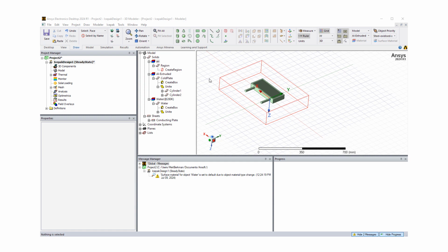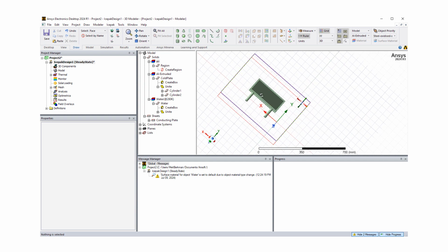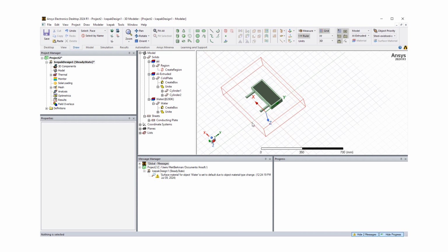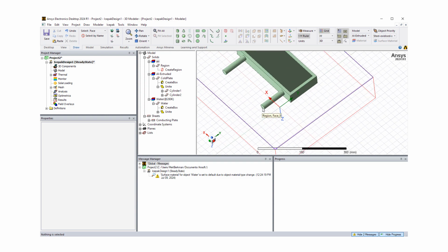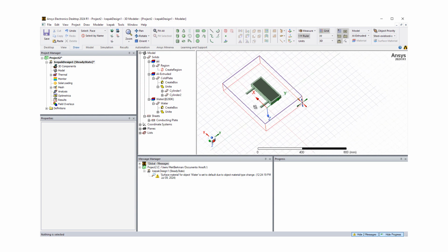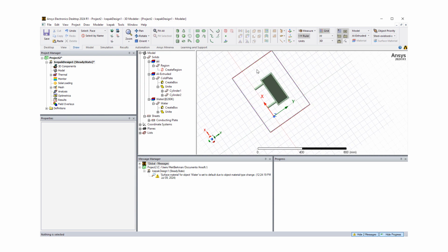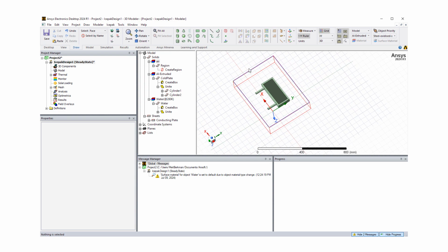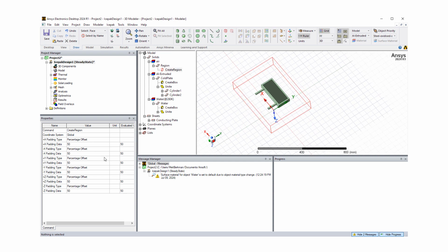In the next step, I'm going to readjust our enclosure size so that it's doing the right things. What I'd like to do is take the face, the Y minimum face, and align it with the inlet of these pipes, and also maybe take the X coordinate, X min and X max, a little farther from the object because we're going to have natural convection in the X direction. So for this purpose, I can click create region, and play with these options.